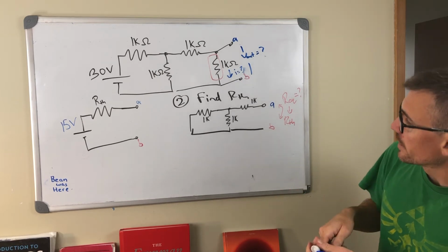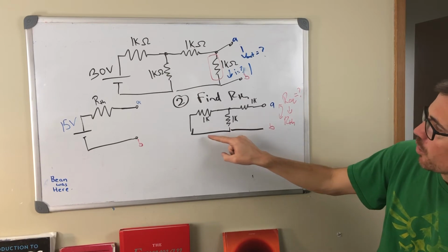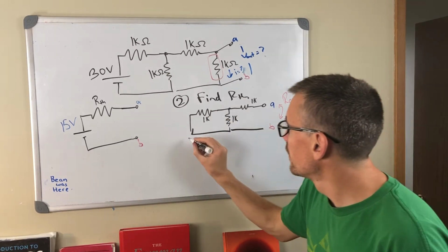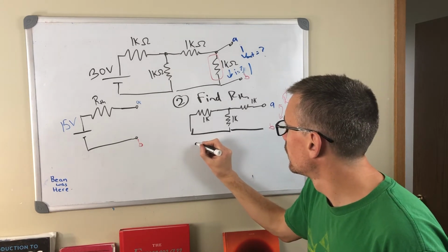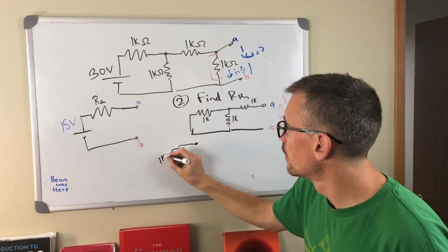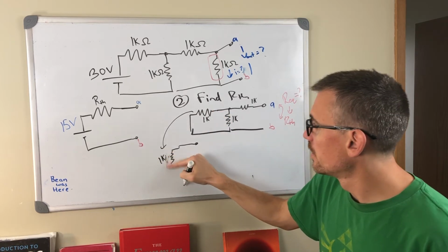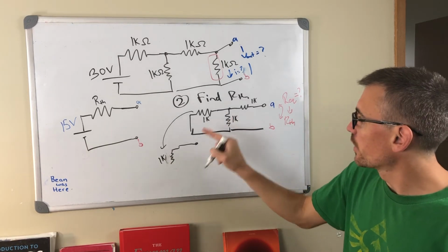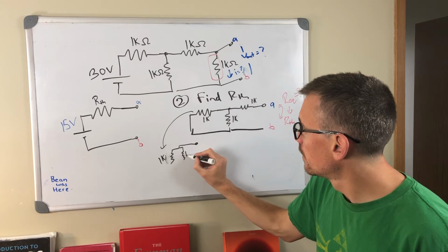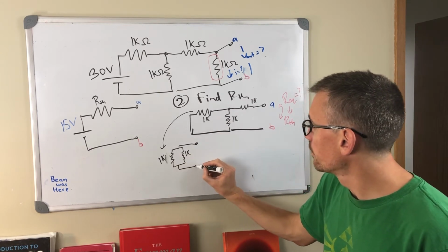So, applying this, let's stare at this for a second. If we look very carefully, we can see this is all one wire. Maybe it's easier if I draw it slightly differently. This is actually the same as our 1 kilo ohm from here, or 1K from there. I'll keep equally lazy and just write 1K. And our 1K here, 1K here, and that goes to B.